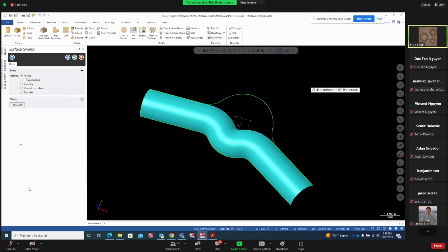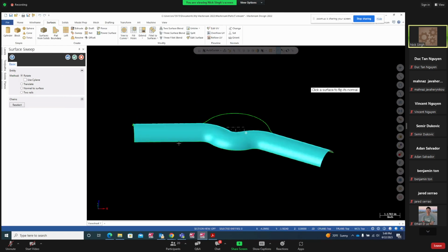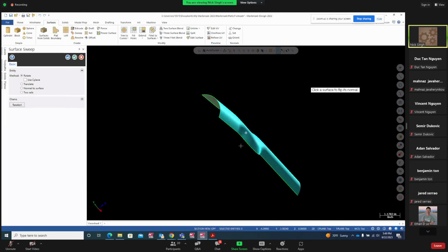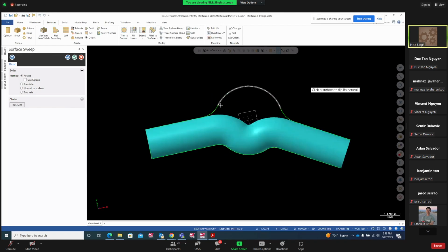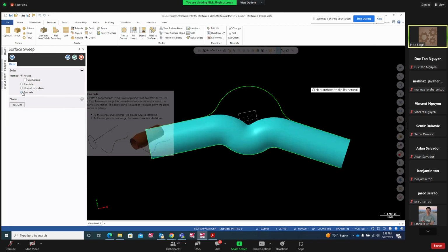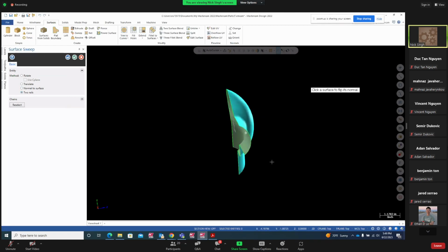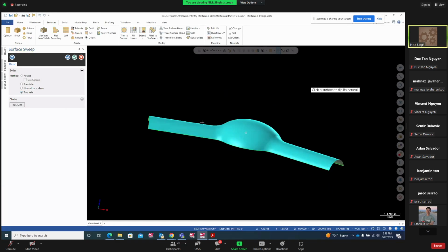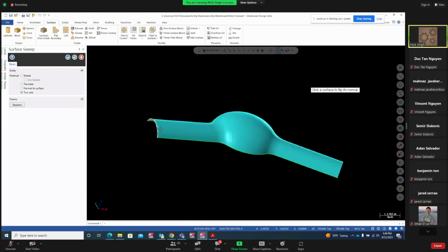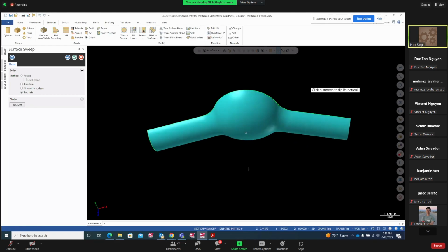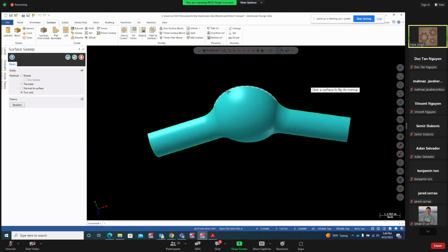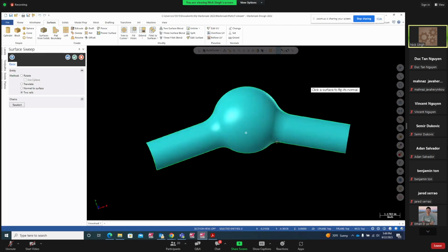So that is gonna give you a surface of this along only one chain, but I have two rails, so you're going to select this option here, two rails. So that will sweep this surface along with these two rails, along with these two chains, because you have two.